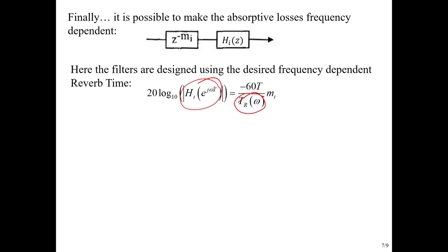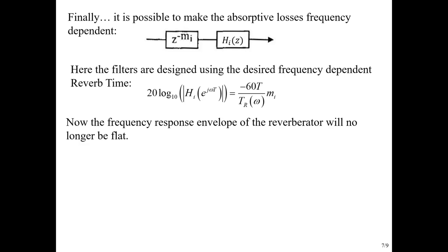and then use that to design our frequency response. And we'd have to use some filter design routines to try to come up with the right frequency design for that. We talked about using things like Prony and Steiglitz-McBride and things like that. So those would be approaches that we could use to achieve a desired frequency response.